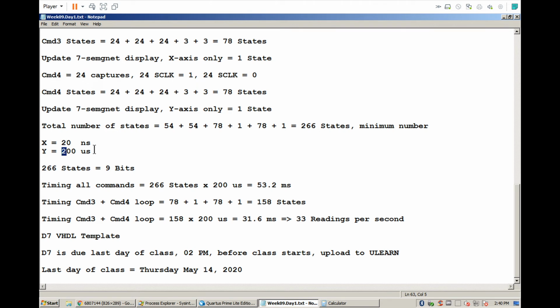You know that from DSP. When you convert an analog value to digital values, you have to obey certain rules. You cannot do it too fast because you don't get precision. But if you do it too slow, you also don't get precision. It has to be just right. And the number that I give you is just right. There's a range of numbers you can use. You can use 200, you can use 300, you can use 250. It doesn't make any difference. As long as you fall into that range, you're good. The moment you fall out of that range, all these numbers coming back are garbage.